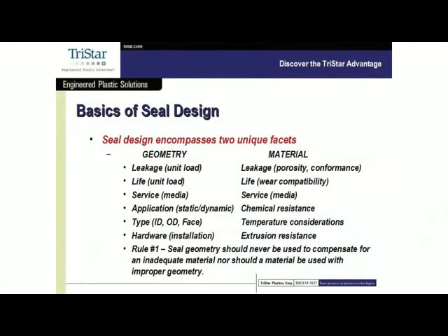Now, in terms of material, especially with PTFE materials, since all PTFE is porous, we need to be aware of what fillers we're using and what technology we're using to make the material. We want to try and get the least amount of porosity, obviously, because if you've got situations with inert gases, for instance, you could be introducing flow paths right through the PTFE seal. So leakage is predominantly controlled by the material. Life as well. Different fillers produce different wear lives.